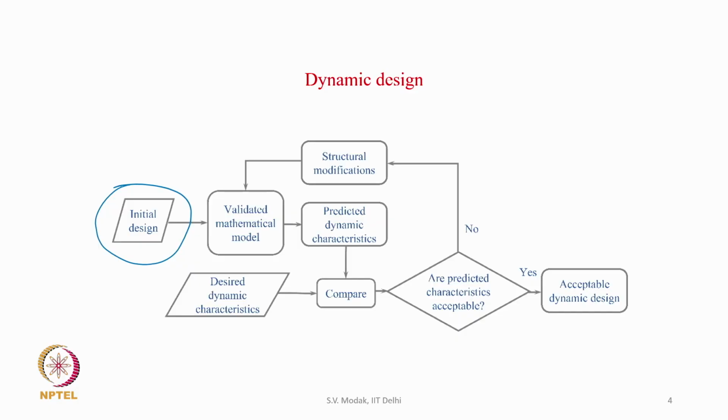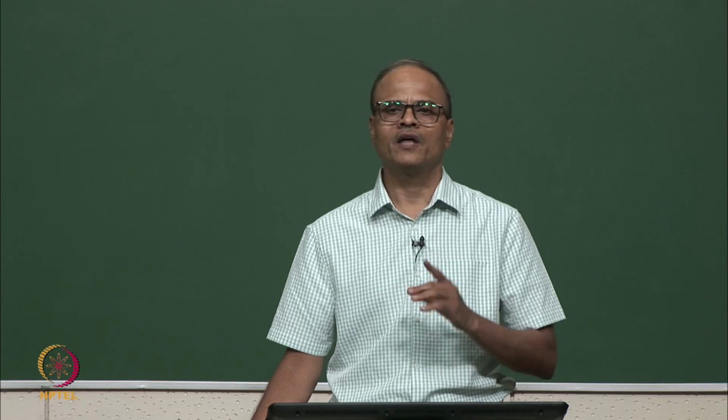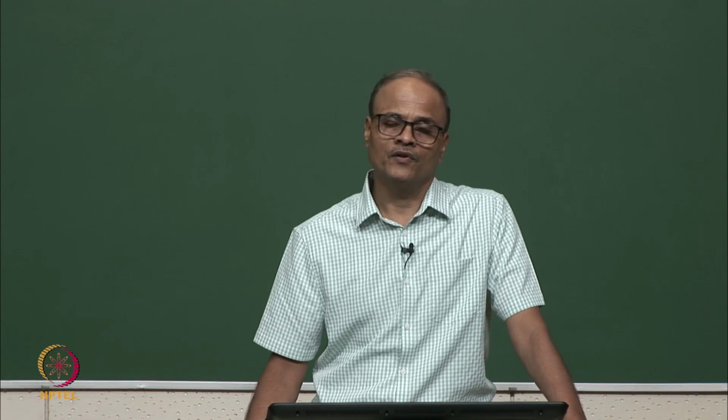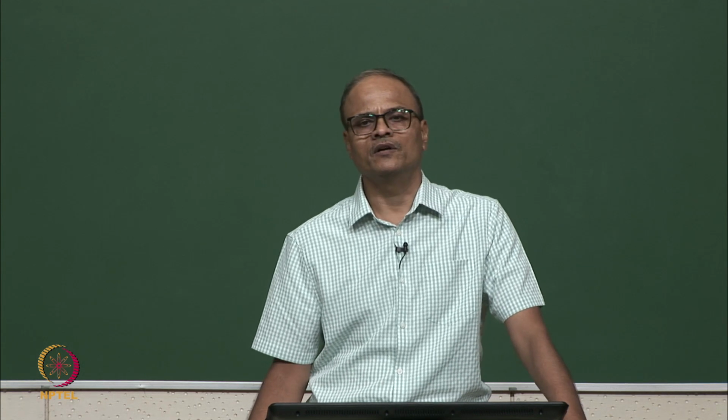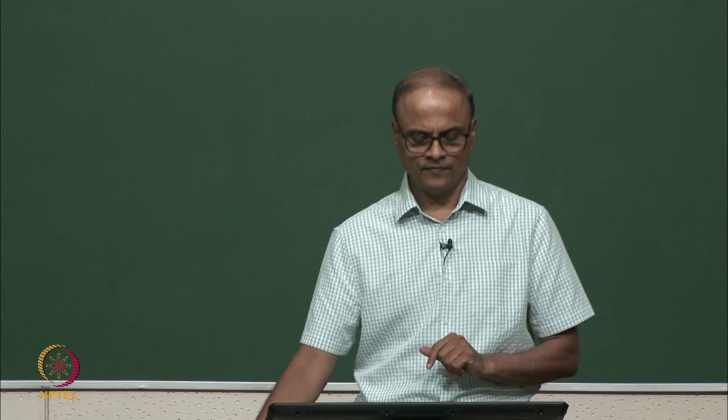Now it is difficult to incorporate dynamic design requirements at the stage of initial design, because the dynamic characteristics depend on the geometry, the dimensions, the material properties and the boundary conditions. All these things determine the dynamic characteristics. So unless the initial design is available, the dynamic characteristics remain undefined. That is why it is generally difficult to take the dynamic design requirements into account at the stage of initial design, and hence dynamic design is carried out after the initial design.